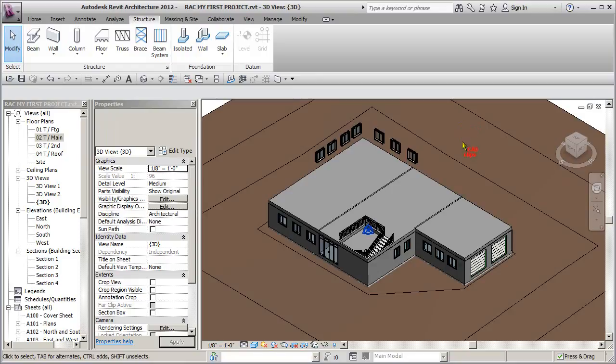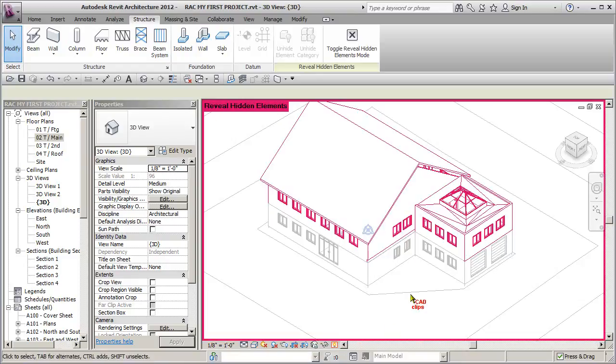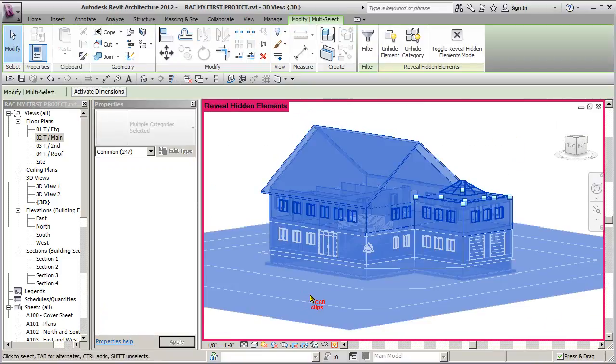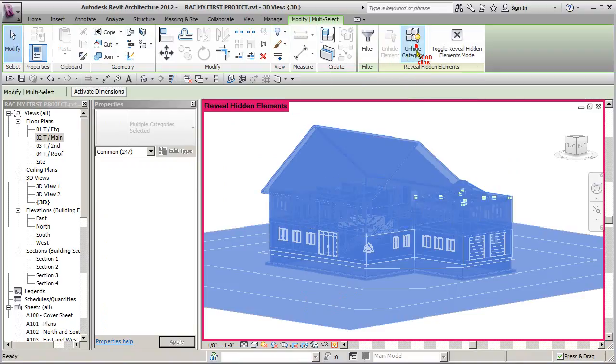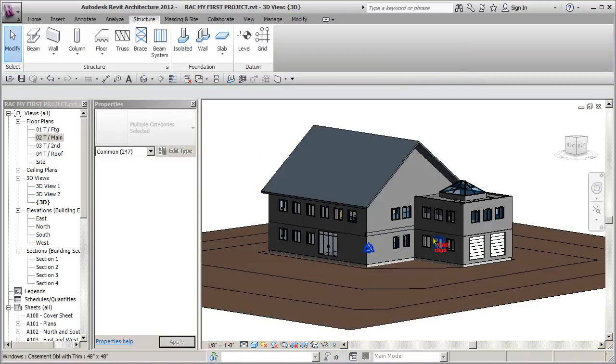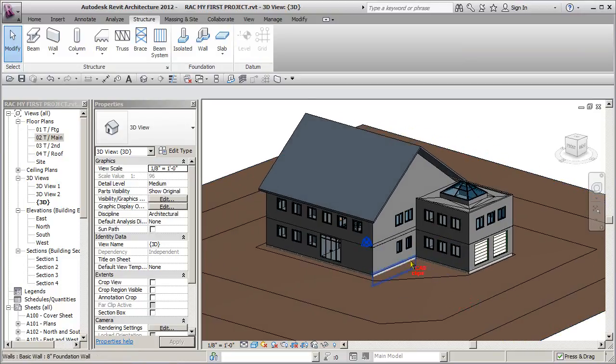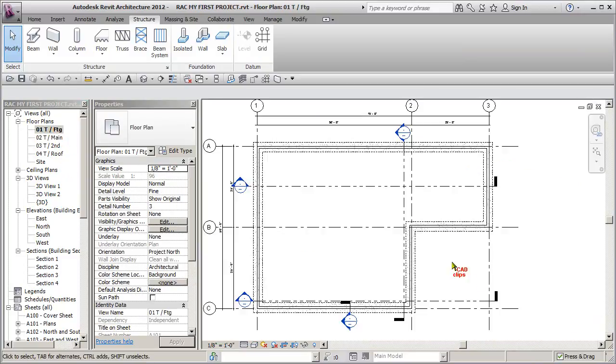All right, so let's go back behind our Wizard of Oz curtain here, and I'm just going to grab everything and unhide the element, unhide the category, go back inside of here. Now, what's next? Let's do our beams that are under our main floor. Now, these ones are different because they're not going to be flush, they're going to be drop beams. So to do that, we're going to go to top of footing.